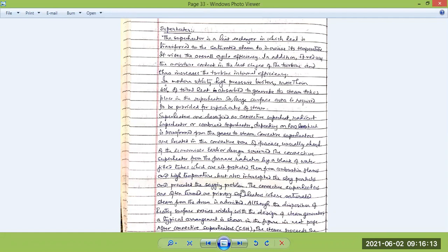The preheated portion of the superheater, which is placed in the convection zone, is protected by water walls or water tube walls. This means the flames emerging from the burning of the coal in the furnace do not come directly in contact with the walls of the superheater, because a number of tubes are also placed between the flame and the superheater.